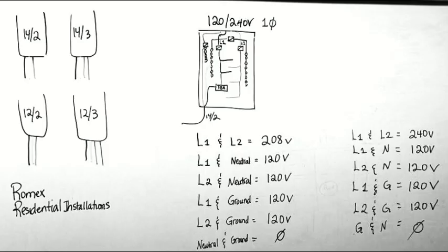Like I was telling you, we want to make sure that our wires are well secured together, because if we have loose connections, see this splice? I think he has to work on this splice. It's not a good splice. And it's crucial because the inspector is not going to take his time and go through each one of your wire nuts. He doesn't have the time to do that. But as a professional, you have to inspect your work, and make sure that your work is up to par, and that none of the things that you do are going to create an accident later on.